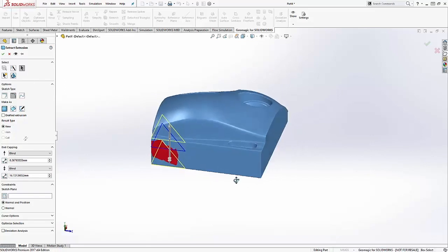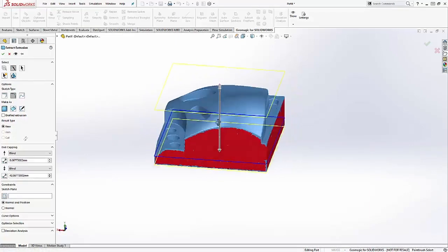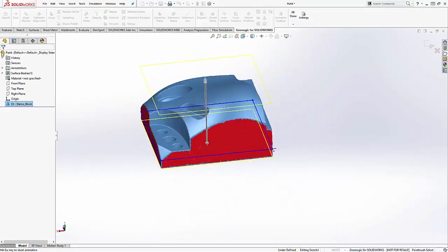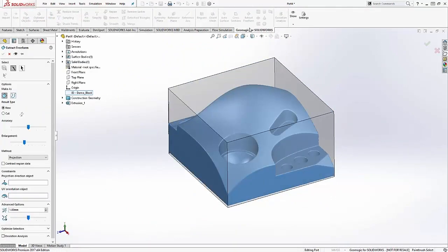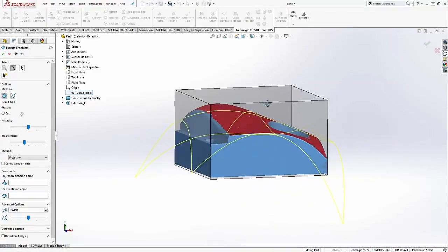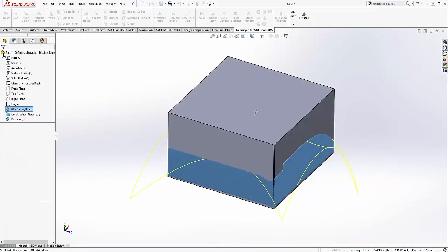First, asking for an extrusion, I'll start highlighting groups of triangles. I've got a lot of selection tools like lasso or paintbrush, but at the end of the day, I want to highlight the outside surfaces, and the program is going to fit sketch data and SOLIDWORKS features to create this geometry. Similarly, I can extract this freeform surface from the top of the part. Now I can create a new surface body or use this surface as a cut right here in the menu.